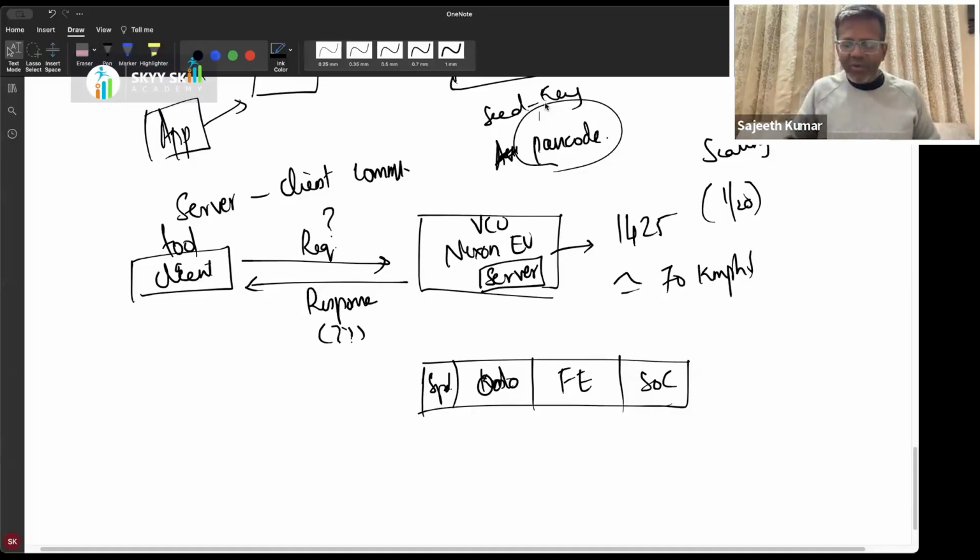Next, I'll have to know which CAN message to capture. And in that CAN message, where exactly is the signal that I need, and what exactly is the scaling factor to extract that signal? For example, is it in hexadecimal, or is it in decimal, or what number system is it in? I don't even know that, right? So there could be so many layers to it. Deciphering a CAN signal is not all that easy. But once you know that, probably you can reverse engineer it.